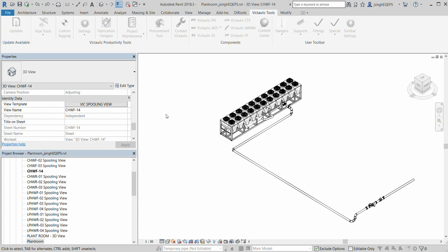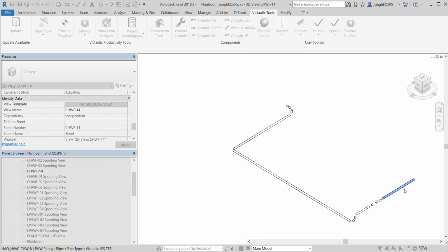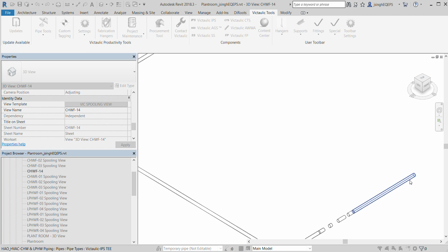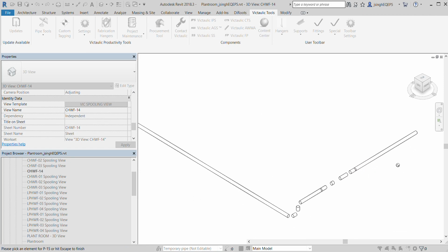You can change it by providing any number here, but my maximum and minimum are according to the supplier. Now I have to split my pipe. You see it doesn't have any coupling here. So let me split by length. From this side I have to start cutting. It hasn't cut anything because they are less than 5940.